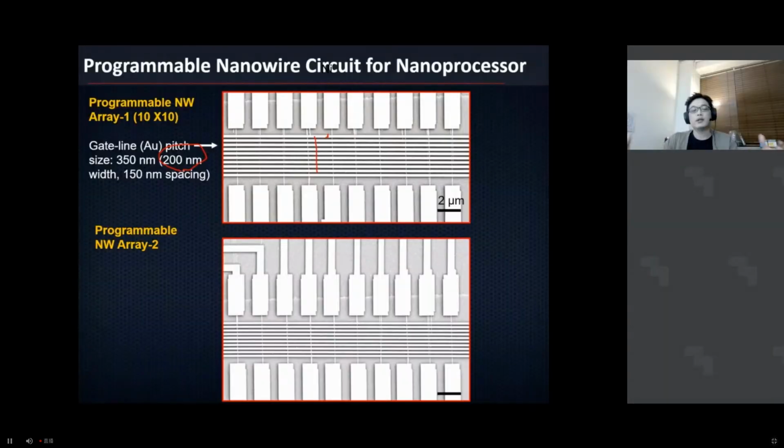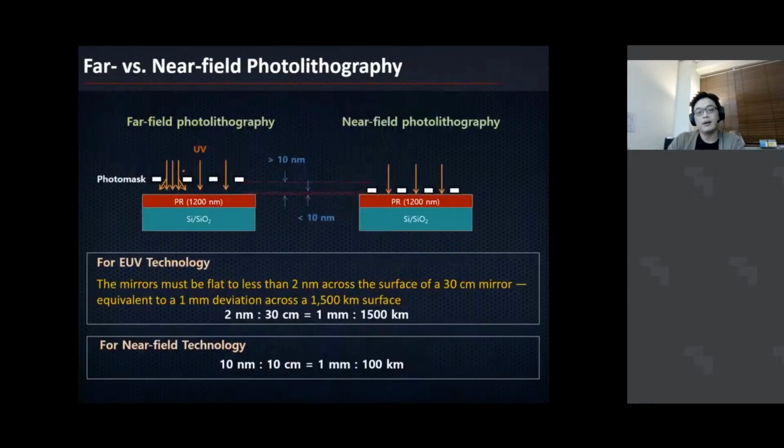So the 1.7 millimeter chip is a combined result of photolithography, which defines the big electrodes, and a smaller one, the sub-micrometer features, which you need to define with e-beam lithography. It's very time consuming, very labor intensive, and also very expensive. You need to use a very expensive tool to define all the electrodes like that. So I look at a different side of lithography as well.